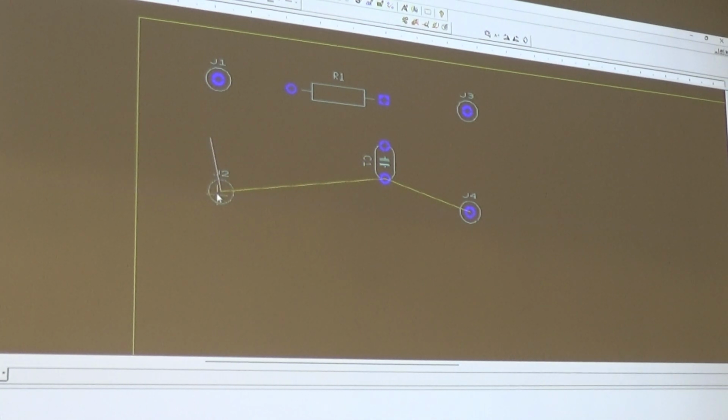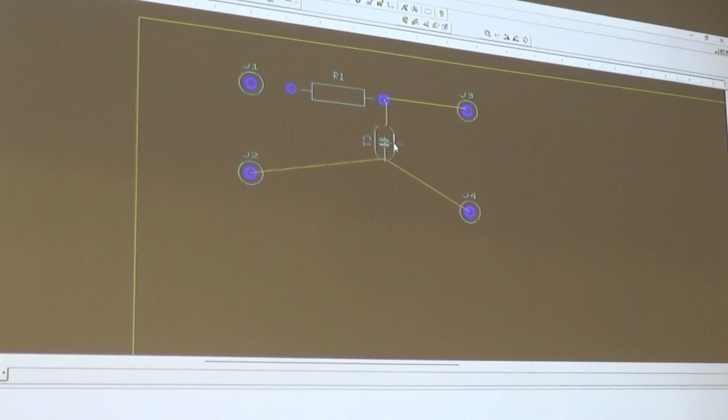So now this is what our board will look like. I'm just making it look pleasing for the eye. So I think my J1 is too far away, so I'm going to bring that in a little bit to make it look a bit nicer there. I want the 2 input pins to line up with one another. So I'm going to drag that across. You can see I've got crosshairs that help me get it aligned. Let's put that there. Let's move my capacitor up a bit.